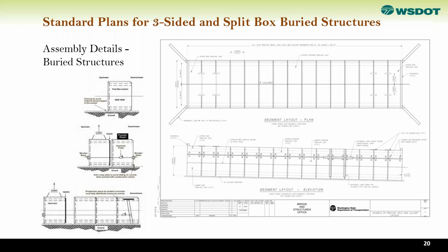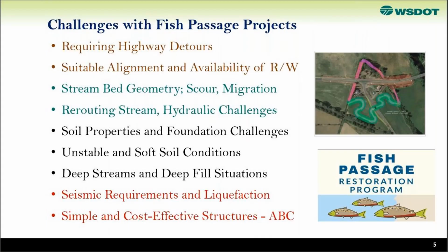I would say that that's going to vary at each particular site based on the impacts to traffic and the fish windows. So it could be 4 to 5 weeks. It could be less than that. Sometimes we're building these in stages and shifting traffic around the site, either with a shoofly, or we're shifting traffic and constructing half of the structure at one time. So it varies on a case-by-case basis.